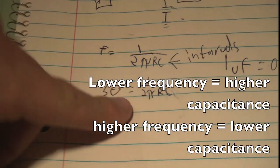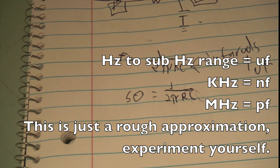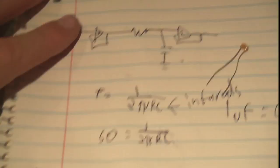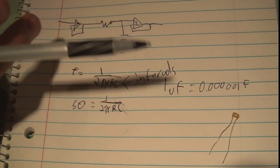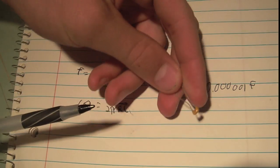And in this case, since lower frequencies usually use lower capacitance and higher frequencies usually higher capacitance, you can go by that rule of thumb. So from that rule of thumb, I'm selecting a 1 microfarad cap. Why 1 microfarad? Because 1's a nice even value, and it's relatively a high capacitance in the scheme of things. Okay, if this was charged to many kilovolts, this might kill you. 1 microfarad is quite a bit of capacitance in the scheme of things.